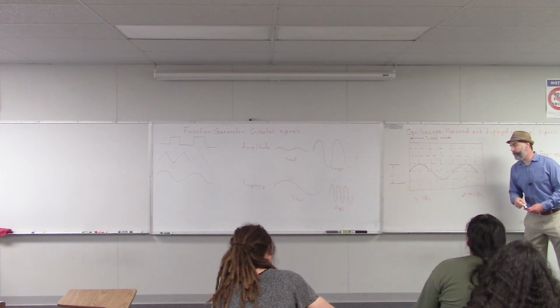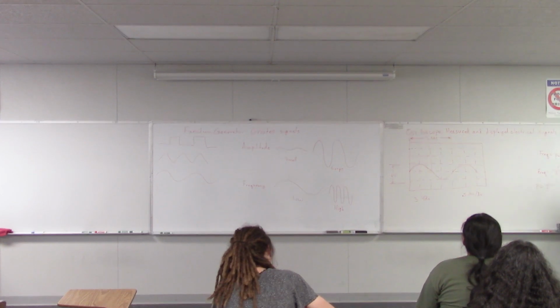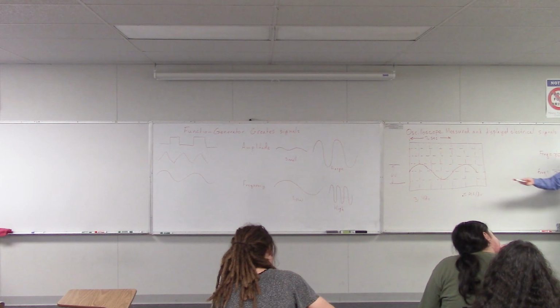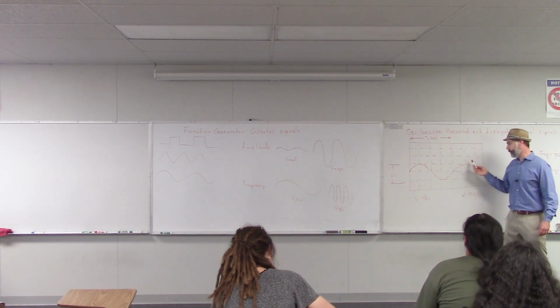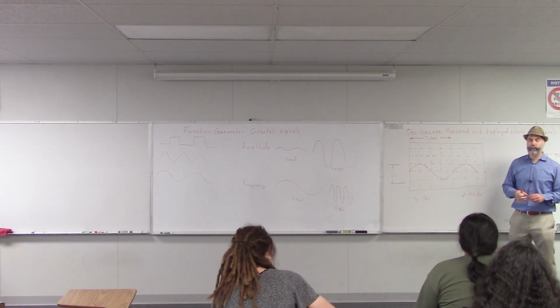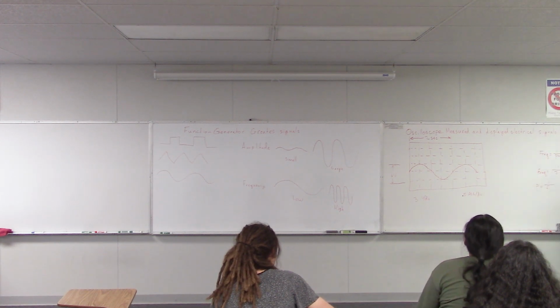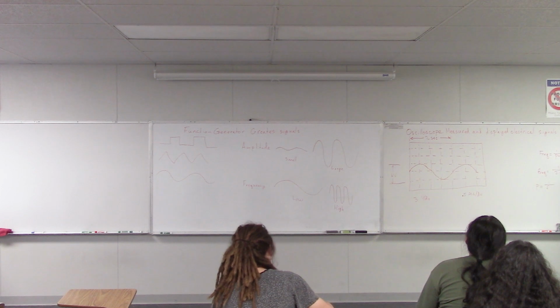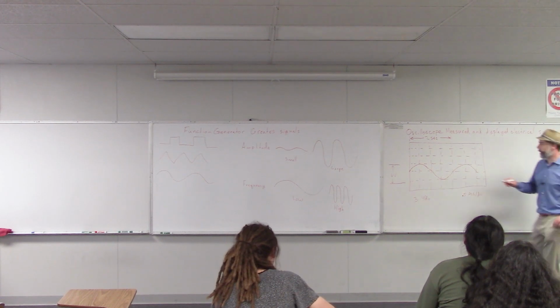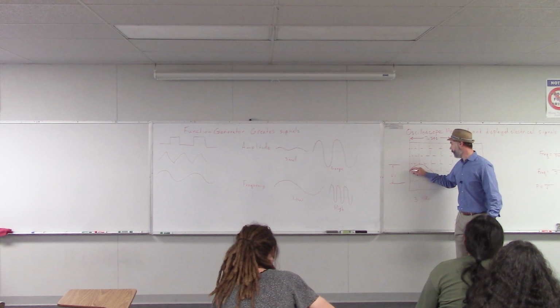Now, the oscilloscope also had more precise measurements, so you might ask, why even bother looking at these divisions when the oscilloscope has these measurement capabilities built in? We could just use the oscilloscope measurements. Well, it turns out that sometimes the automatic oscilloscope measurements can make mistakes, especially if you have a wave that's not perfectly flat.